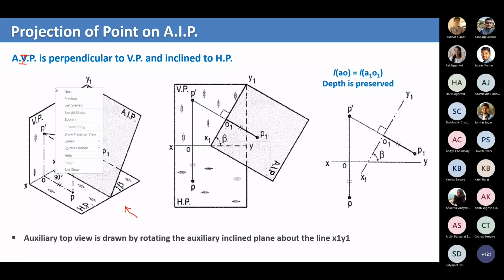So now we have got our x1, y1. The key point here is how we convert these perpendicular planes VP and HP into our 2D figure. We rotate our horizontal plane about the line XY, in this direction.